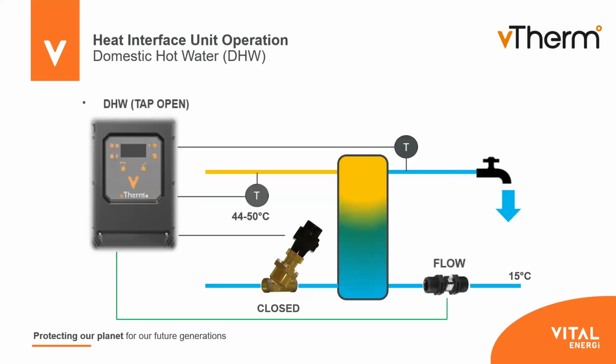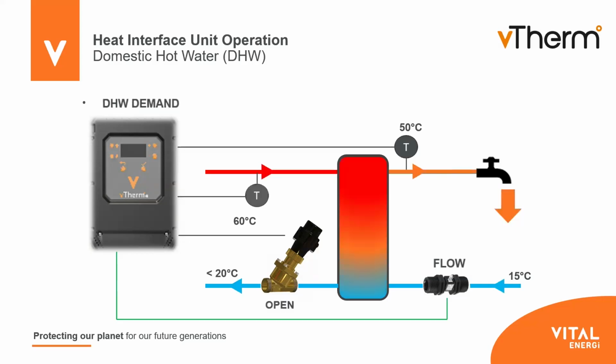So as we bring the tap on, we will get a domestic hot water requirement, because the flow turbine will then start controlling the control valve and actuator, and therefore typically you'd have nice hot water flowing out at 50 to a maximum of 60 degrees. 60 is normally for NHS applications, 50 to 55 is common for domestic, and then of course you'll have anything maybe up to 20 degrees on the return.